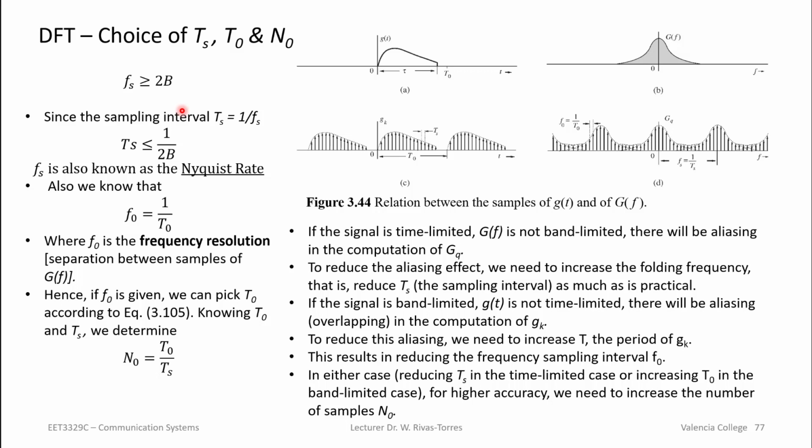Your original signal back. I am not being very rigorous. Those of you who have taken a signal processing class, those classes should go a little bit more rigorous than what I'm doing here. But just know that your sampling frequency has to be 2 times the bandwidth or greater so that you can always get your signal back when you go from the frequency domain to the time domain, or whatever it is you're trying to reconstruct. Okay.